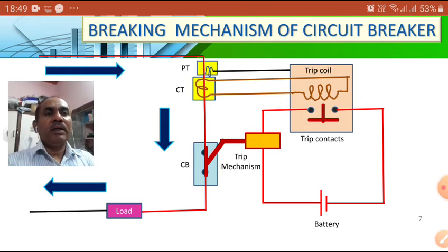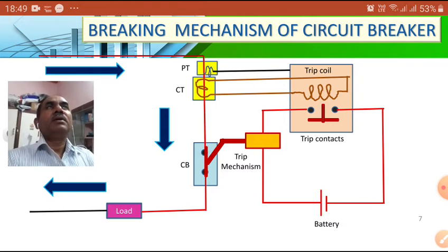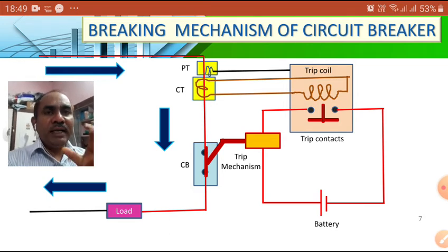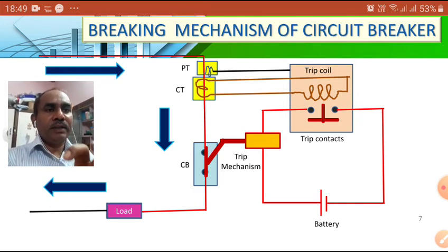Automatically, this weakens the arc for the next few microseconds. Then it will automatically quench the arc when it comes to the zero crossing period. We can learn this clearly with the help of diagrams. This is the basic idea of the vacuum circuit breaker.